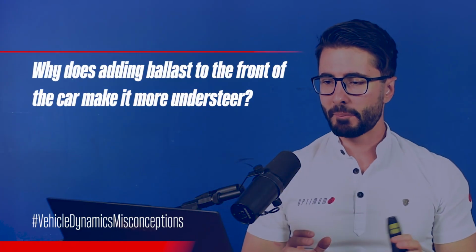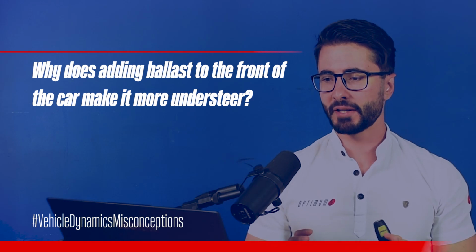Why does adding ballast to the front of the car make it understeer more? So basically the question is asking, when you change the weight distribution of the car, let's say that we move it forward, why does it induce more understeer? Well, it all comes down to vertical load sensitivity. That states that as you increase the load on the tire, it is less efficient in generating force.